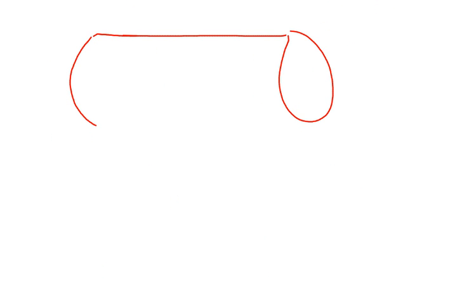Okay, so let's see if we could work that out. When you have a shaft that's in torsion, there are two very important angles here. So here's what we're going to do. We take the shaft again, before we apply any torsion to it, and rather than marking it with a bunch of squares, all we do is draw two lines. I draw a line right down the side, lengthwise, and then I draw a line that represents the radius.